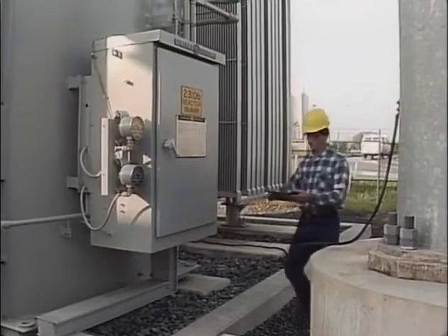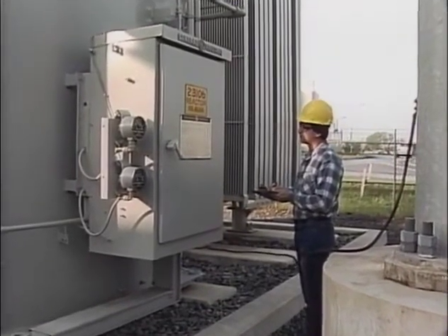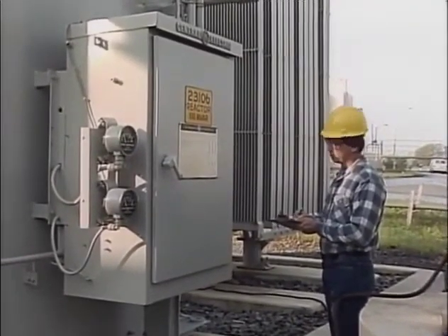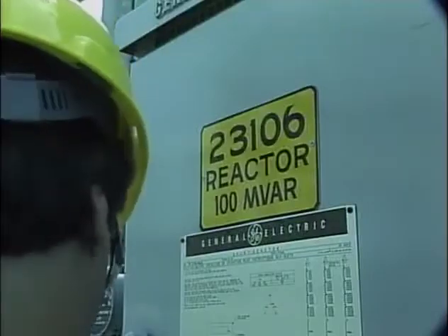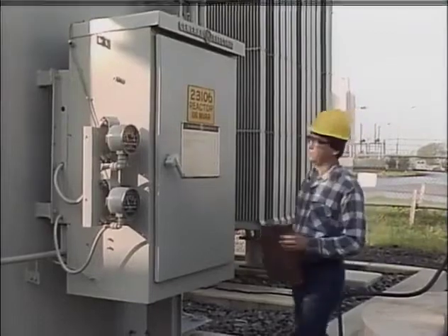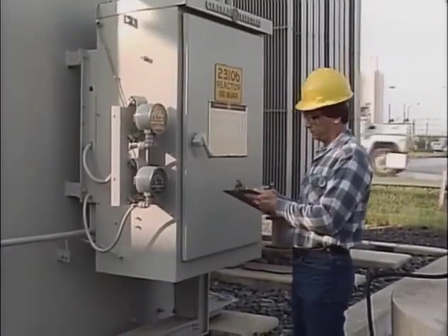In general, shunt reactors require very little maintenance. Typically, all that's done on a routine basis is a visual inspection while the reactor remains energized. Here, a worker is going to inspect an oil-insulated shunt reactor. An inspection generally includes recording various indicator readings and checking the condition of the reactor. An important first step is to identify the reactor that is being inspected. After that, readings and conditions are often noted as you walk around the reactor.